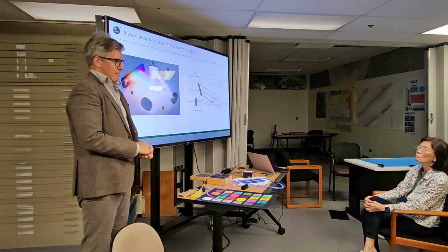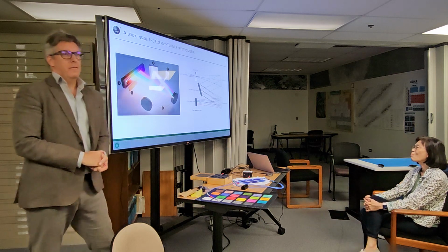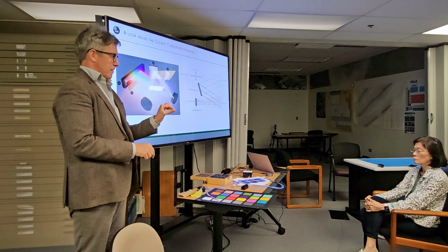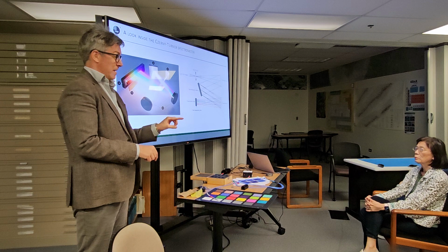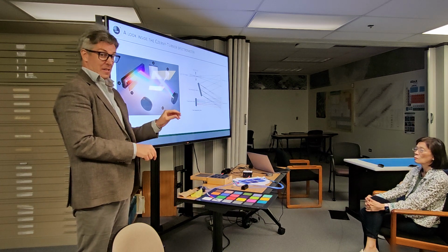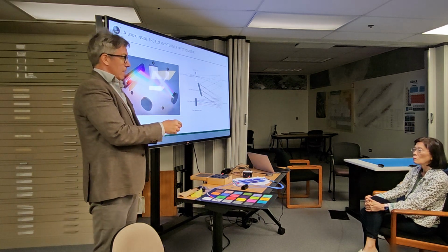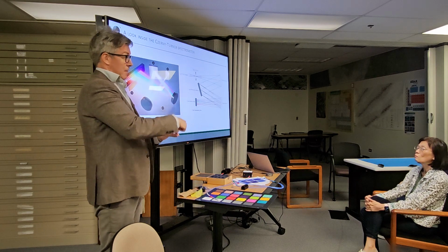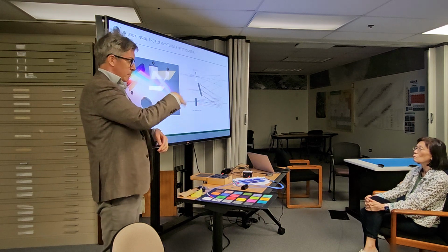CMOS stands for Complementary Metal Oxide Semiconductor. In terms of the physics, they work in the same way. We've got a light-sensitive crystal, an alloy, which has either an excess or a deficit of a dopant, meaning an excess or deficit of electrons. And we shine photons of a particular wavelength, and that can cause loosely bound electrons to be boosted into the conduction band, and then in the presence of a bias voltage, we can sweep them up, and that's our signal.